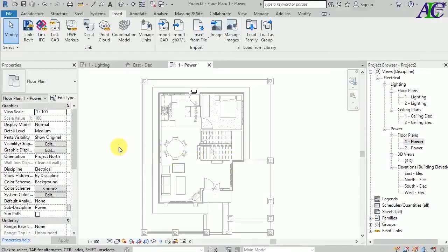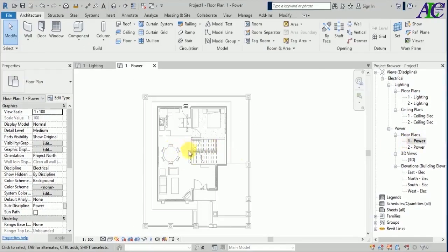Okay, I'm going to mention that each receptacle should be mounted 45 centimeters above the finished floor. For the wet areas, that's different. For the living room and bedroom it is 45, and for the wet areas like the kitchen and bathroom it is 120 centimeters. So this is the norm that I am going to follow.